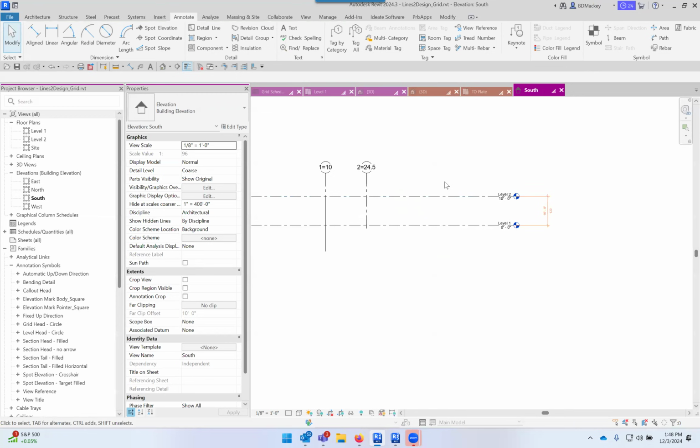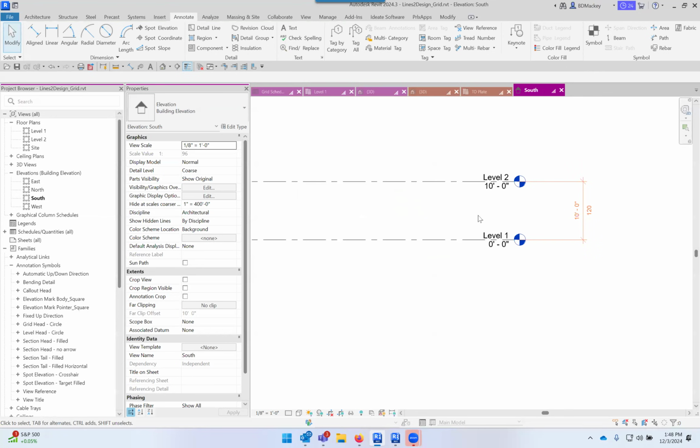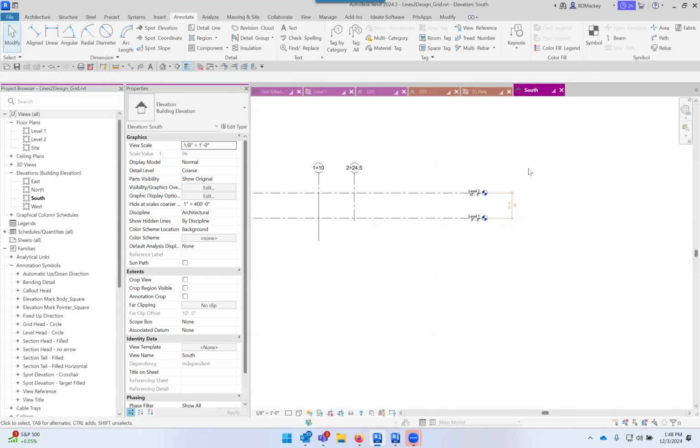Most of my clients have created from there, and I laugh. I come in and I do this. I'm like, yeah, you guys need to delete level 2 and recreate it. They're like, but we have hundreds of views associated to that. I'm like, I know, I'm sorry, but your level 2 is not level. There was some sort of bug, and the Autodesk programmers were like, that's not supposed to happen. Levels can't be drawn not flat. I'm like, well, they are.